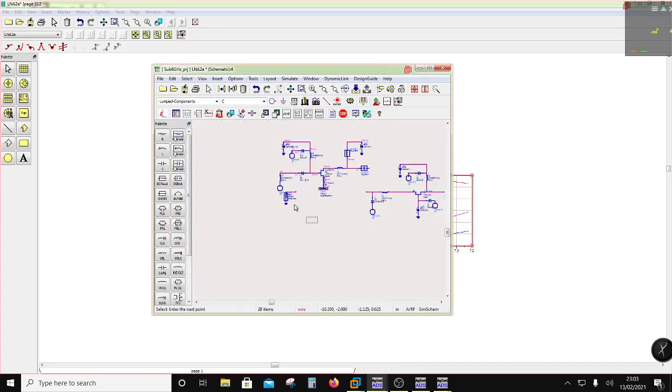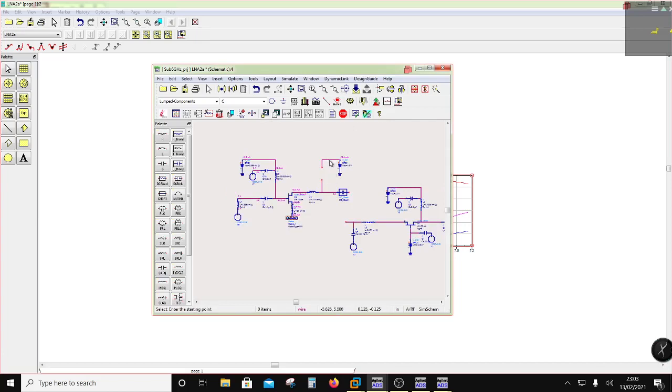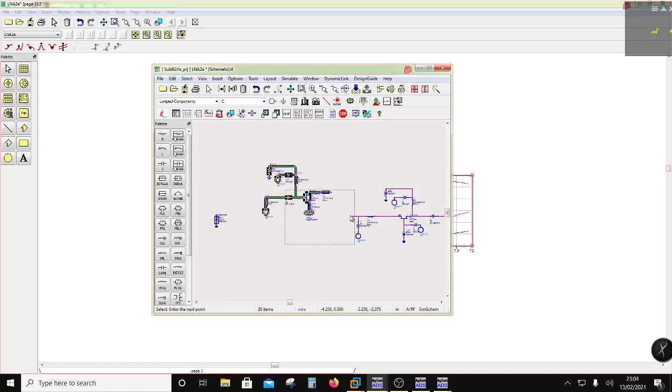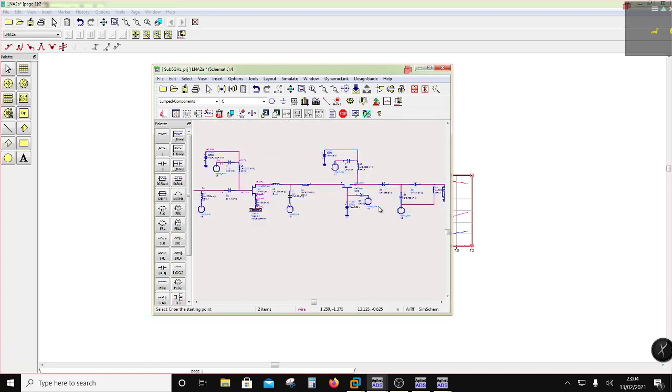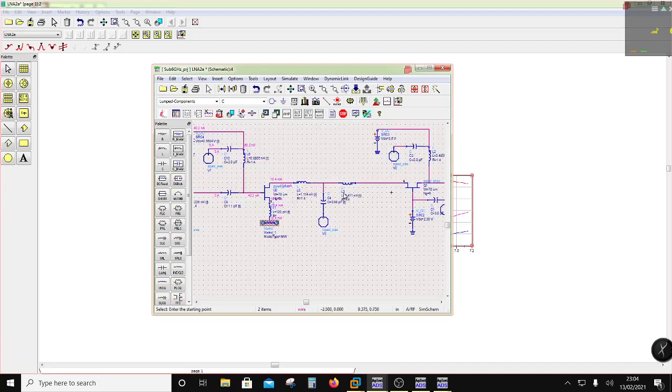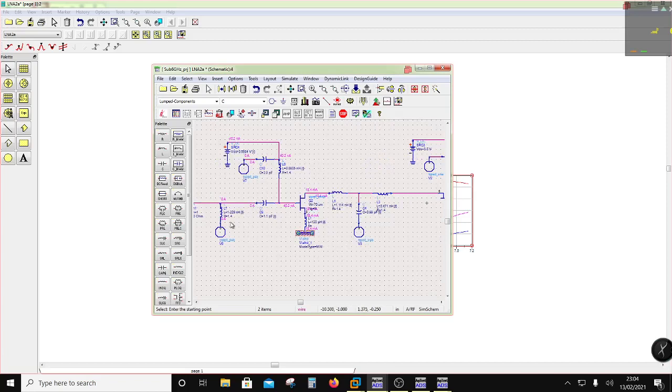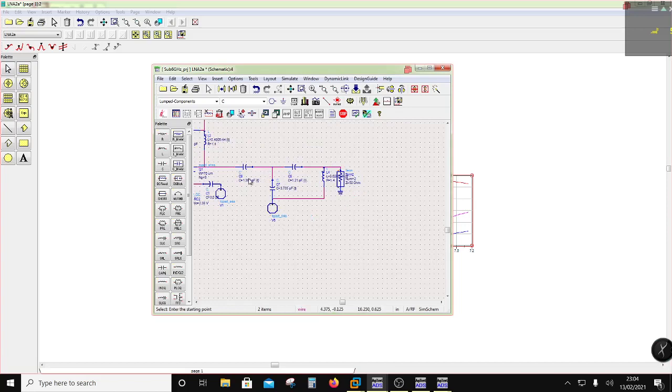Okay, so up till now everything is kind of with a certain system. Now this is not going to be there because this voltage is setting that, and this is also not there. So all that remains is this guy. Now you are looking at a two-stage, right? And we should know that L5, L3, and C4 is the interstage. C9 and L7 is the input, and C6, 7, 8, and L4 is the output.